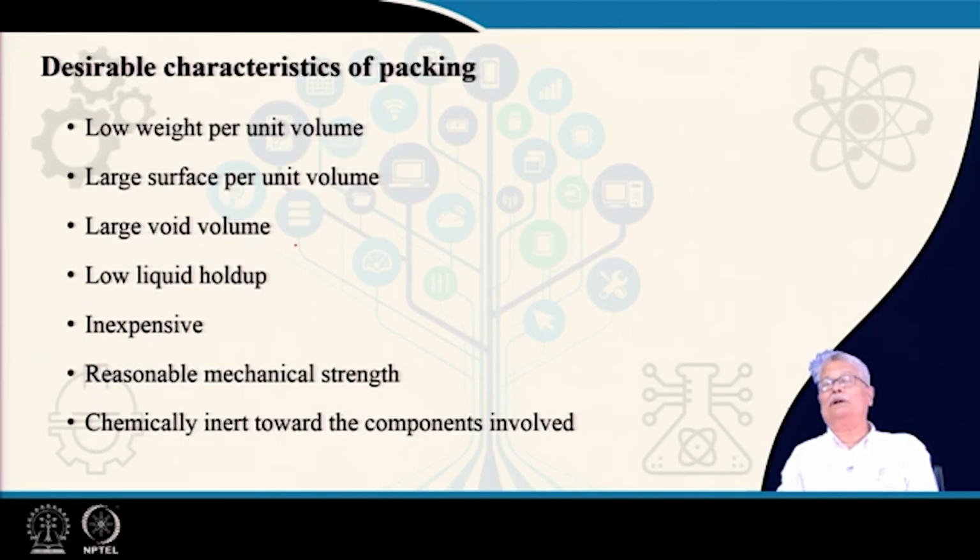You must remember one thing, whenever you are talking about the pressure drop in case of this type of beds of vapor liquid flow, the pressure that is lost by the gas is primarily at the vapor liquid interface.